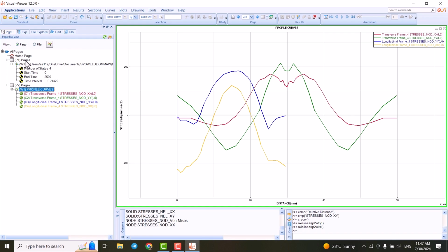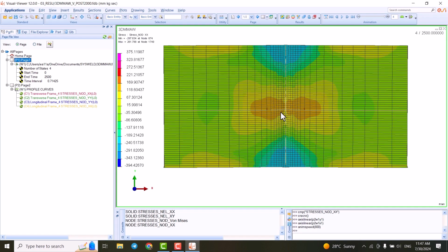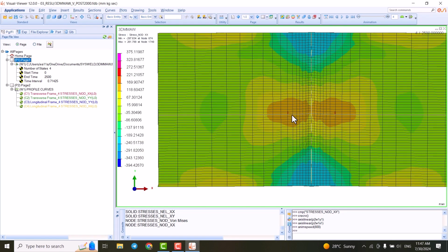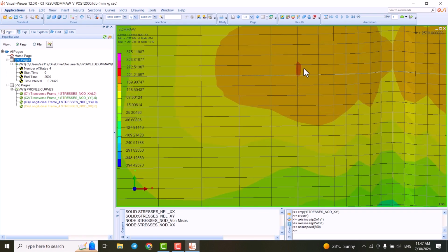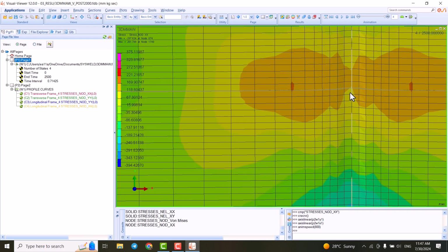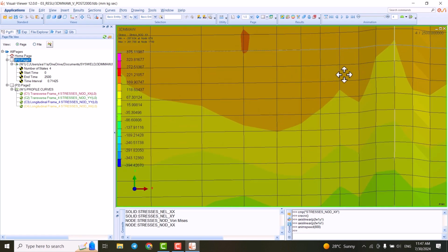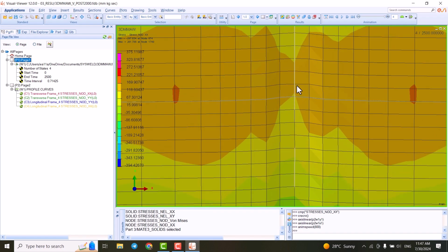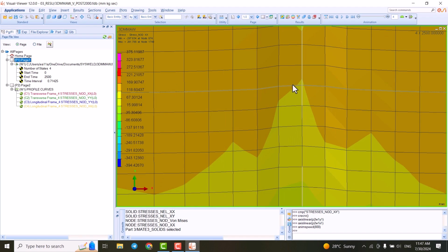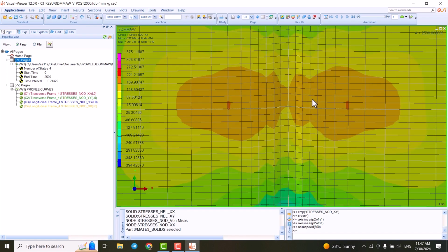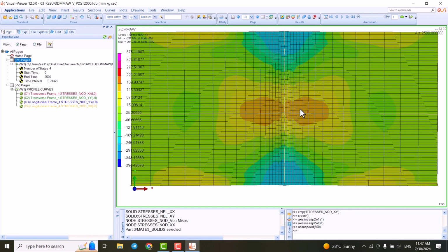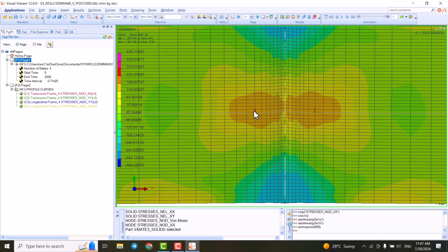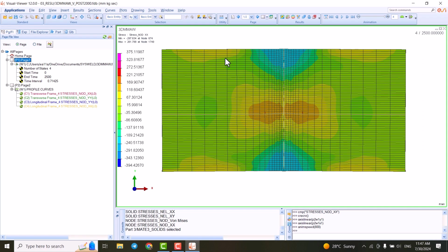you're going to have higher stresses. So we come back to the page 1, and you see here the highest stresses should be here. So if we select it here, it would be better, because you see the path we selected doesn't contain the highest stress in the middle, and that's why we have a reduction. But generally it is okay. So if you are doing the analysis and creating the path, you can create this line, which is better.